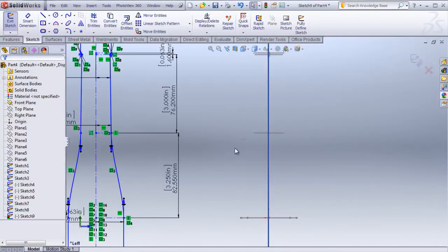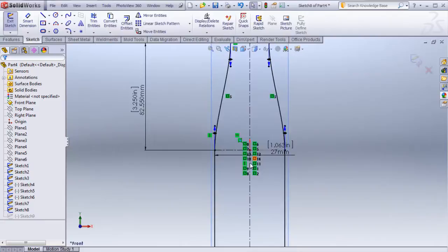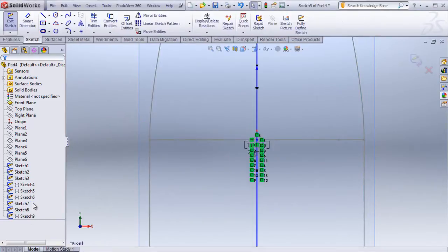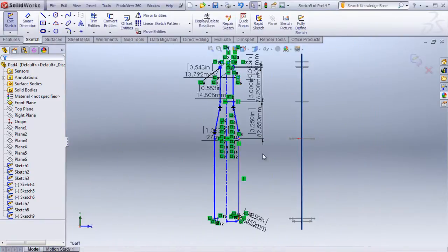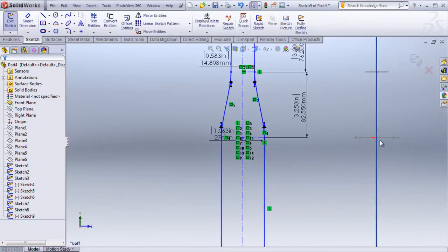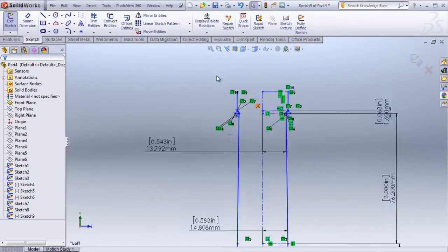And once I do that, if you might have paid attention on sketch 8, where this really meets this point, it starts actually at the origin. So if I grab the sketch from this particular point on the right plane and drop it on this one, that will work. So I'm going to go on sketch 9, on the same plane. If I grab it from here and move this point onto the origin of this sketch right here, then it will actually work. So I'm going to do exactly the same thing.